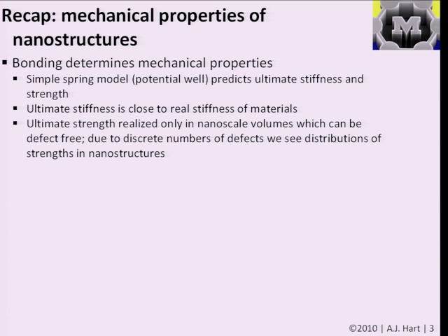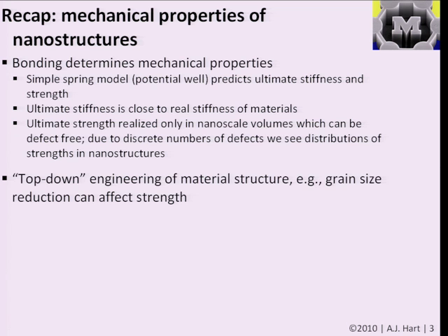And in general, we would have our highest strength, as you could imagine, if we had a defect-free structure, and then the strength would decrease to, you could say, the strength of a bulk material if we had an increasing number of defects to approach the average concentration that we would see in the bulk. And this has been seen for a lot of materials, and is something that you certainly would pay attention to when engineering these materials at the small scale.